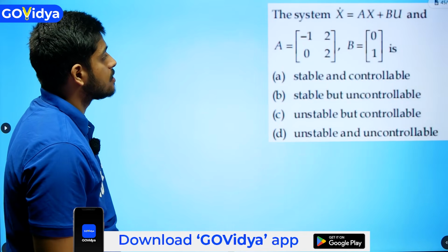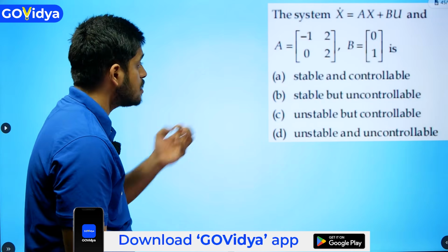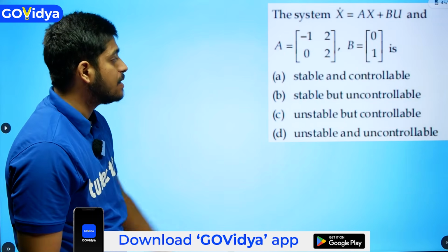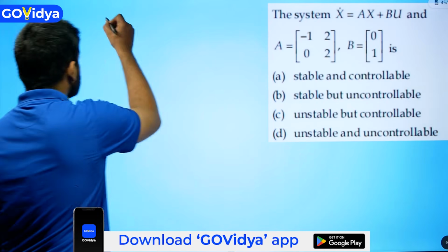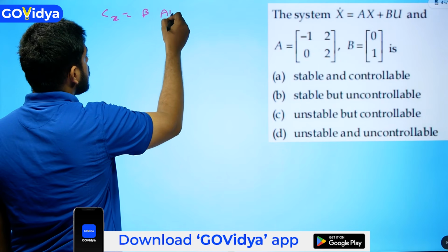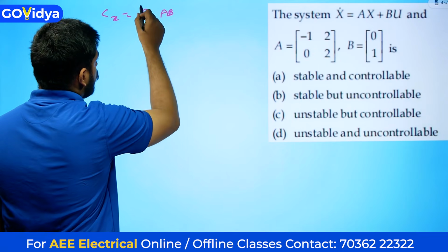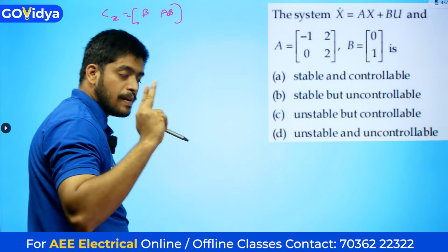So the system X dot is equal to Ax plus Bu, the normal state equation. A and B are given. We need to find the stability and controllability. First we'll do the controllability. Cx is equal to B, AB, A square B, those all are there, but what do we require? Only B and AB. Why? There are only two matrices given here.